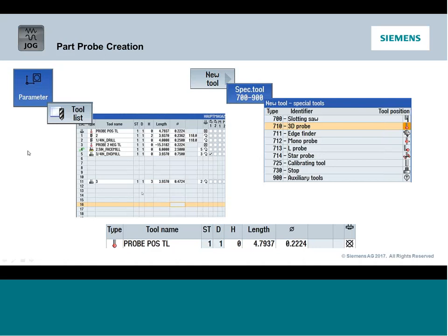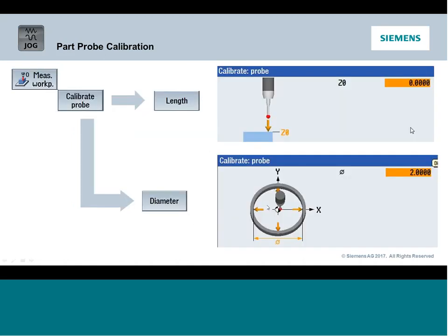Now, I will warn you, if you happen to have, let's say, Renishaw or Marposs, and they installed their cycles in the control, you're going to have to calibrate the probe twice. I can't seem to get any of these probing manufacturers' custom cycles to write to the same variables we write to during calibration. So they have their own calibration cycle. If you calibrate with our cycle, our routines, that'll let all our cycles work. But the Renishaw cycles or the Marposs cycles won't work.